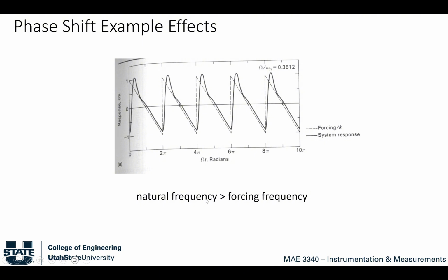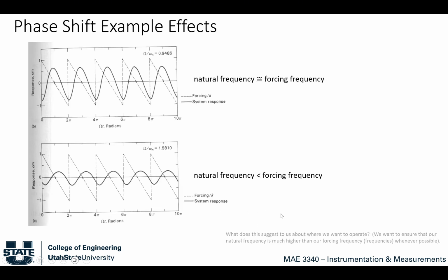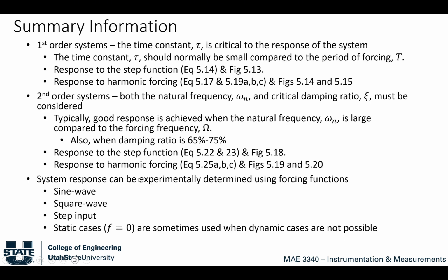So this is what you should take away from this whole discussion. Try to make your measurement system, especially if it's first or second order, higher in its natural frequency than the forcing frequency. Otherwise, you're going to run into these cases here.